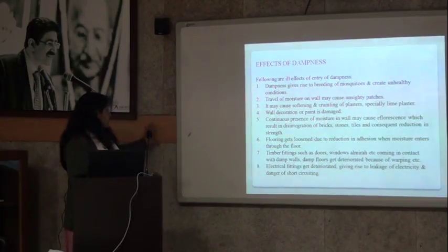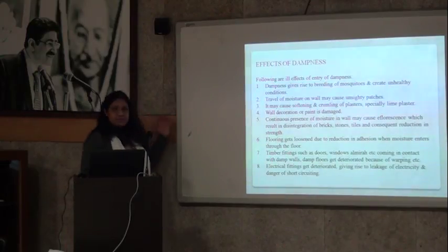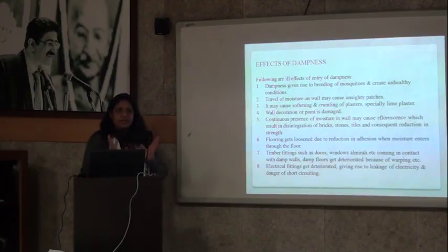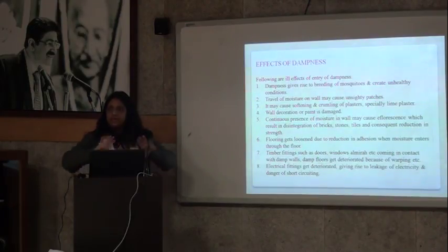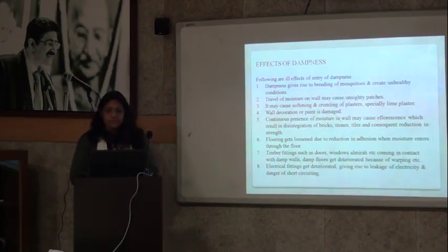is done here, one band. If the dampness comes behind this wall to this panel, then it will get warped. It gets warped in the surfaces. It will not be in a straight line.